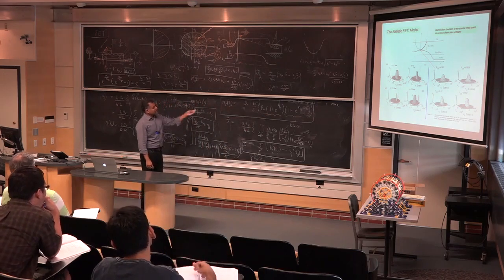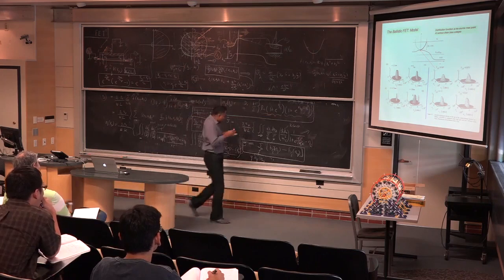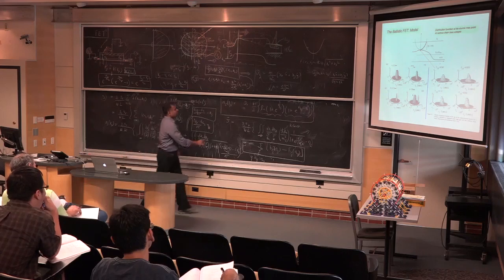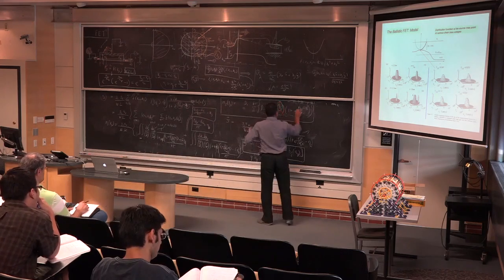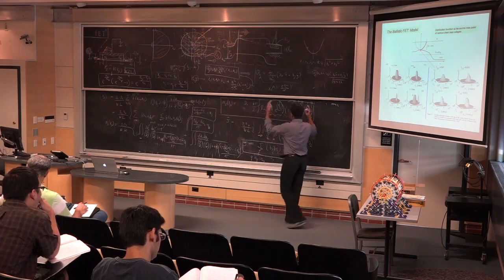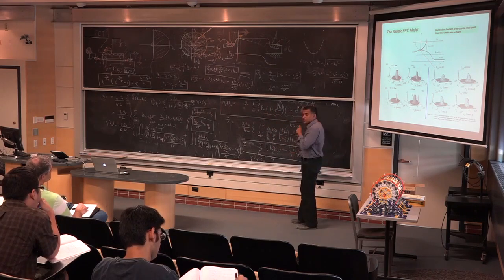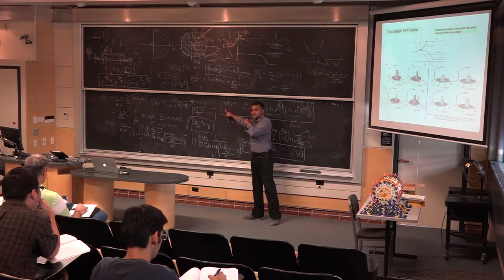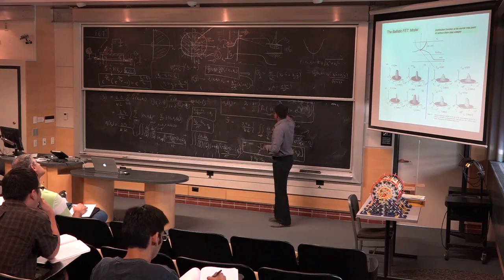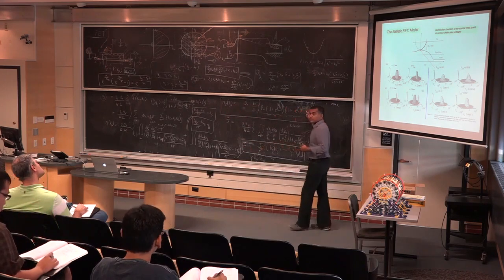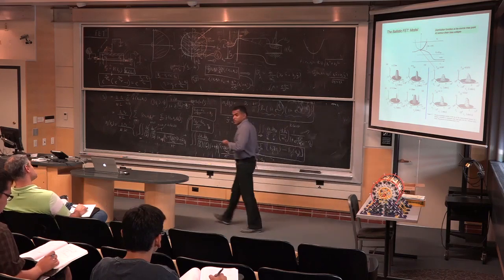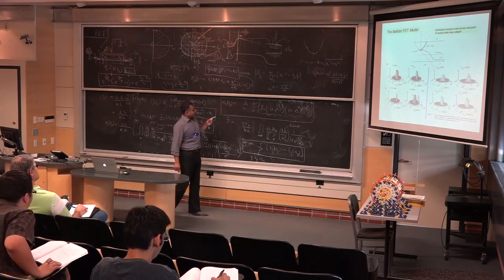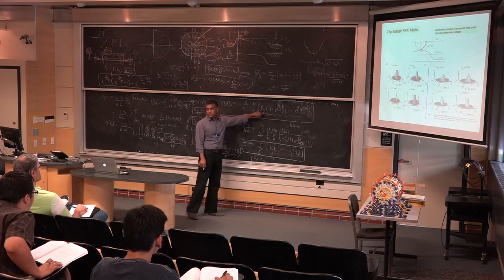And it might look like a rather complicated equation to solve now because we're saying, look, you know everything in this problem except, in some sense, how does this depend on drain and gate voltages? Clearly the drain voltage dependence is sitting here, right? And the gate voltage dependence is sitting there. Right? So you need to solve this equation to get what is eta sub s as a function of gate voltage and drain voltage. Right? And this equation might look very formidable, right? I mean, it looks like, oh, yeah, how do you solve this equation? It looks formidable. But actually, you'd be amazed, but this also has a closed form analytical solution.